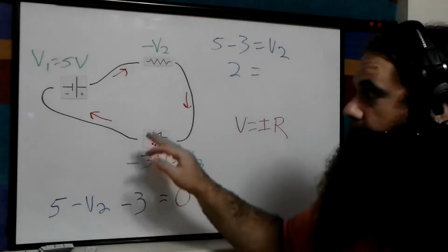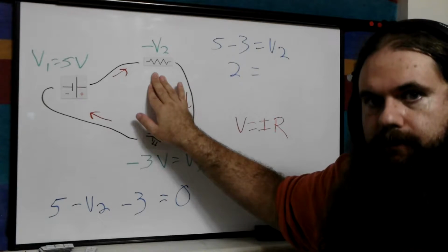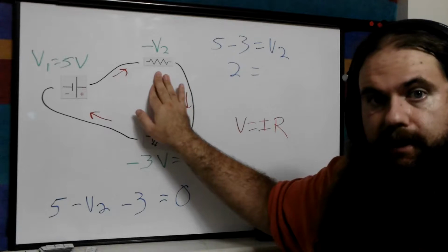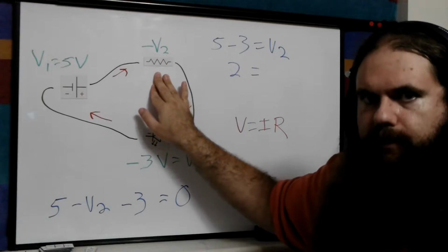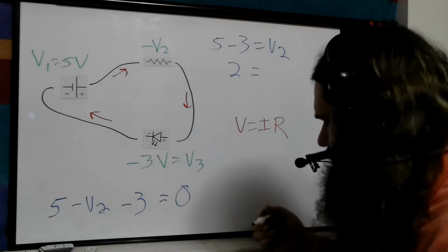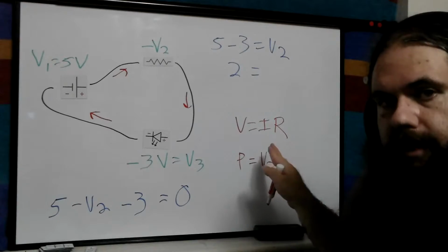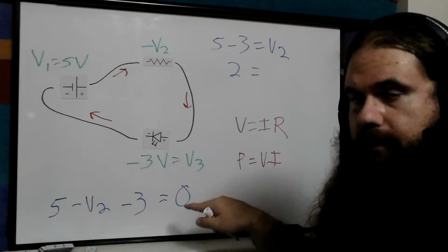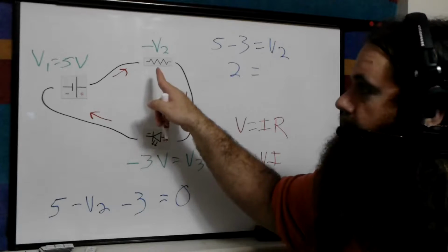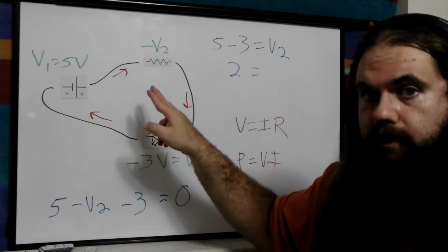You can also use it for getting voltages to say, let me make sure this resistor is not going over its power limit, such as if this is a 0.25 watt resistor, one of the most common types. So you have V equals IR, and then P equals VI. You don't even need the resistor. You can calculate how much power is voltage and current, and you know whether there's too much power going through here for any resistor that you own.